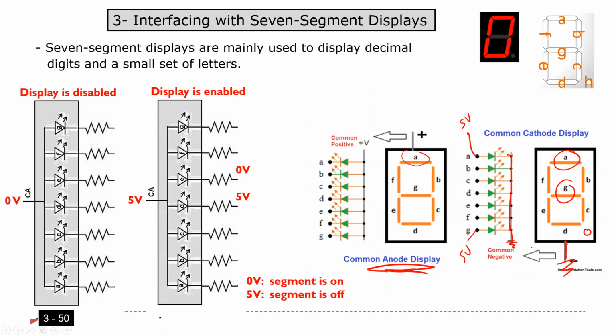As you see here, guys, if you want to turn an LED on, the voltage of the anode has to be greater than the voltage of the cathode. Is that okay? So this is one 7 segment. We have another 7 segment, which we call common anode. Again, guys, when you buy a 7 segment, we have 2 types. Internally, either they connect all the anodes together, or they connect all the cathodes together. There's a small difference between how we use them, as I'm going to explain right now.